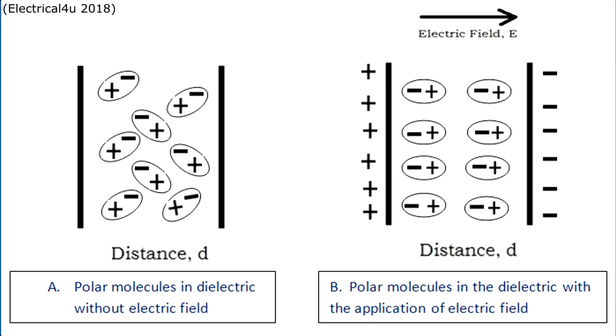When dielectrics are placed in an electric field, no current flows. So hence, the positive charges within the dielectric are displaced minutely in the direction of the electric field, which goes from positive to negative, and the negative charges are displaced in the opposite direction. Therefore, there is a slight separation of charges known as polarization, which in turn reduces the electric field.